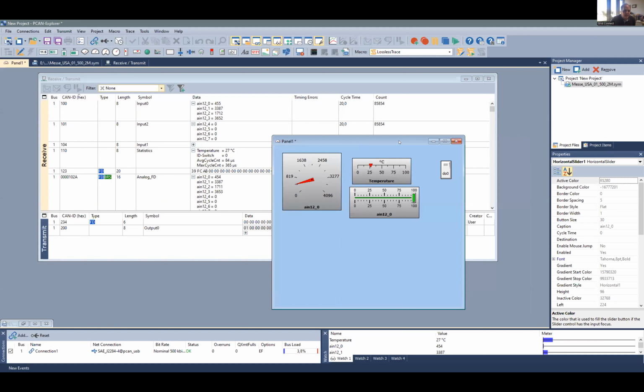Let's see, here's another one. Can we use PCAN Explorer 6 for transmitting and receiving J1939 PGN messages and for testing UDS? No, only PGN messages, UDS not from the PCAN Explorer. For UDS, we also have our own protocol stack, which is also free if you own a hardware. You must develop your software by your own using the UDS API.